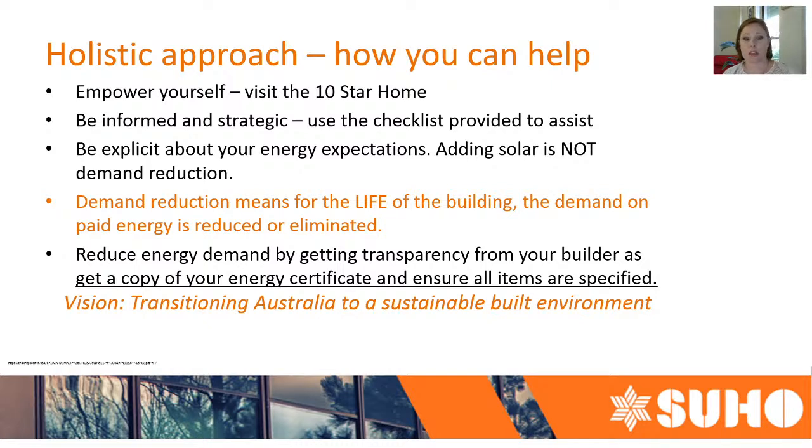Demand reduction means for the life of the building. So again, tying into that solar concept, things like that do have a lifespan on them. So you might have to replace your solar panels in terms of 20 years or so. If you're highly insulating the building and doing it right from the word go and got this passive approach, then your building remains that high performance for the long term. So you're getting your return on your capital investment.